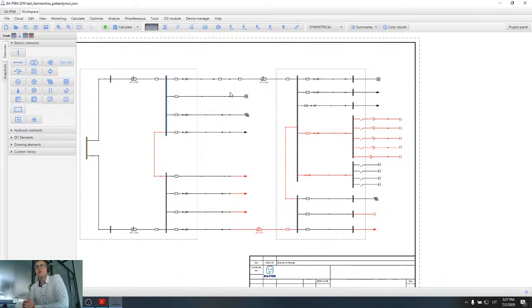And maybe last questions, then we'll go to our analysis, and other questions I will leave for later. So the question is from Mr. Pedro, and it asks, could you tell us something about capacitor explosion when there are harmonics? So actually this is a similar question to Mr. Thomas's, and as I have mentioned, a high level of harmonics overheats the capacitor.